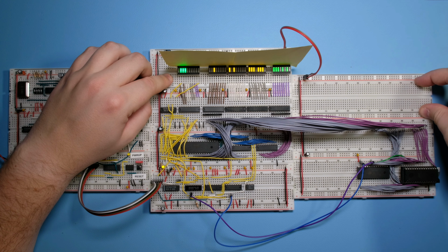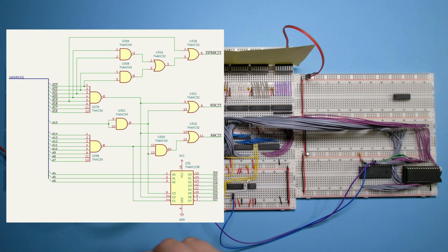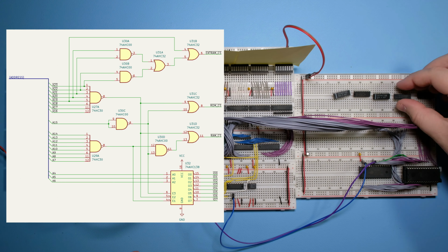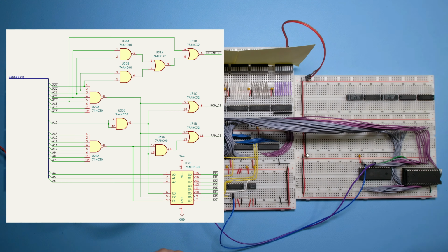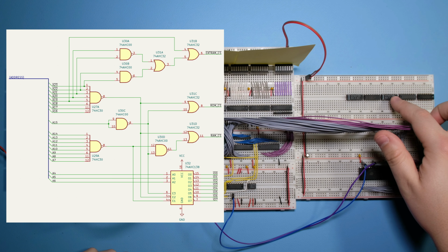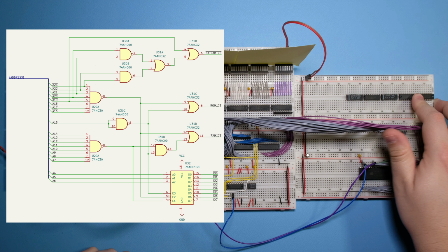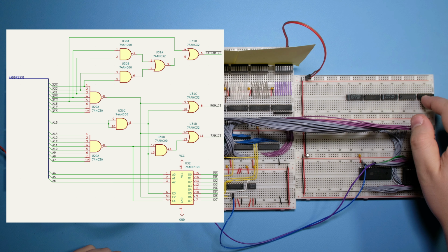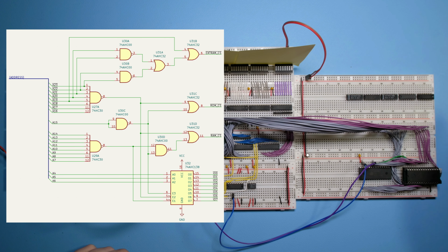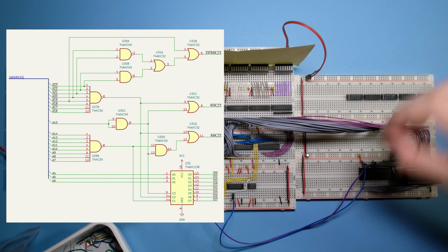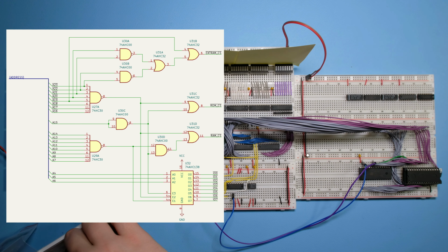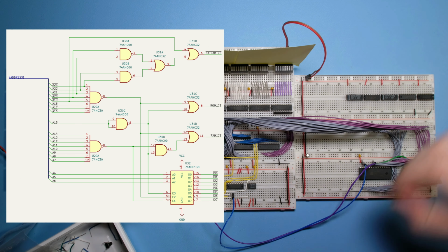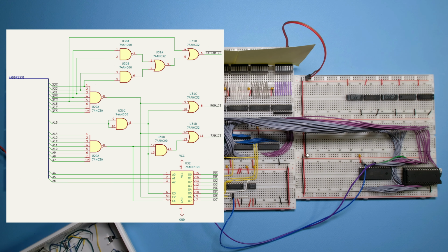Now what I'm going to do is work on implementing this circuit here. There we go. So these are all the chips we're going to need. I'm using HCT chips for now because that's what I have in stock, and we'll see about upgrading these later. So they all need power and ground and decoupling capacitors. There we go. Now we have to connect everything up.